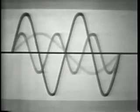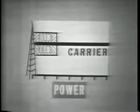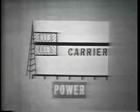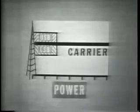Let's look at it in a little different way. And we'll begin to see some undesirable things about the conventional AM signal. After the sidebands are generated, the carrier is not required for transmission of the sidebands. Now, since the carrier is constant in amplitude and in frequency, it contains absolutely no information at all. So why transmit it? Yet 2/3 of the total power is wasted in transmitting the carrier.